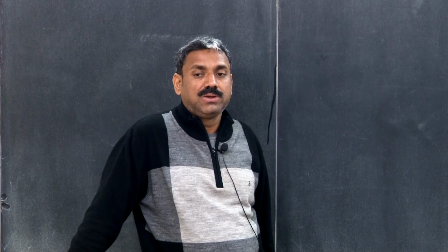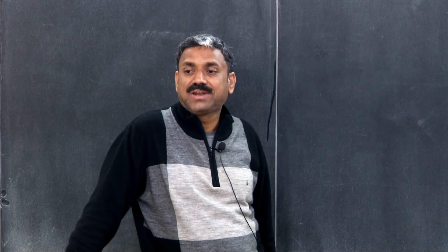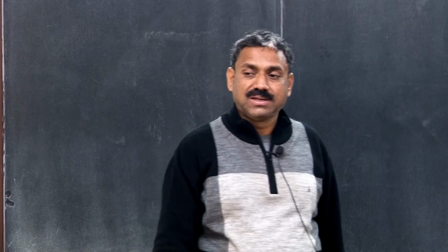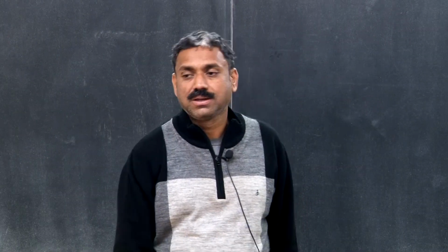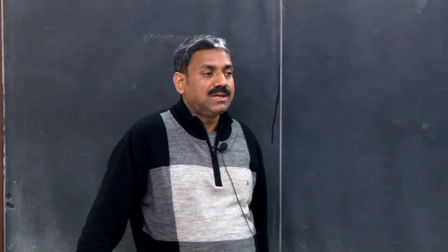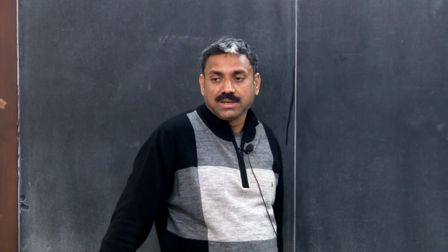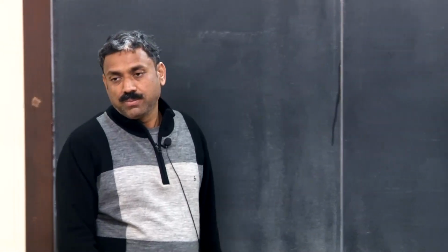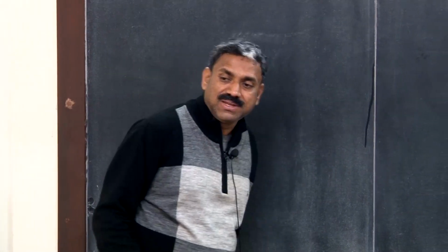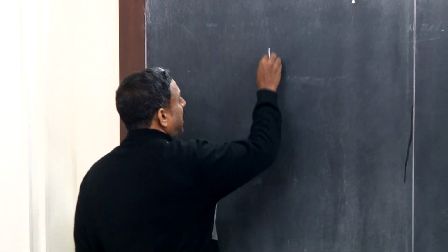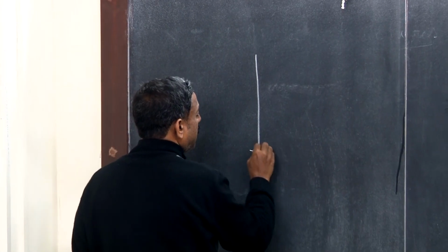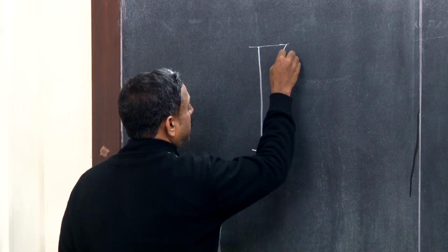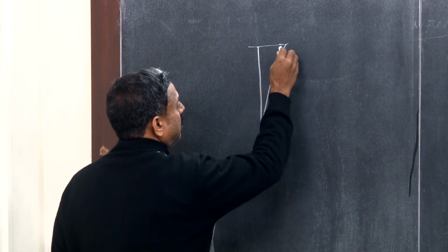Please recall that we know the beam bending equation: EI d4w/dx4 is equal to minus q(x), or if you want to write in terms of bending moment, then EI d2w/dx2 is equal to minus M(x). So, M is the bending moment. How is this bending moment coming there? We considered a column, and then we perturbed it and wrote down the equation.